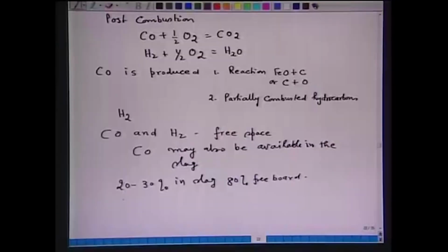So, the requirement for post combustion is just opposite to that of the oxidation reaction. That means now what you require? You require to inject oxygen at low speed. If you want to utilize the oxygen completely, then oxygen should disperse well in the freeboard, or disperse well in the slag if post combustion is carried out in the slag.